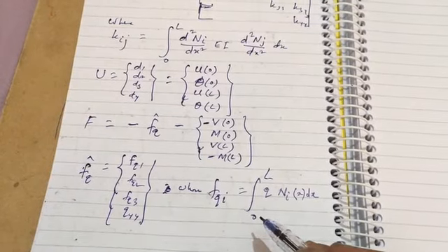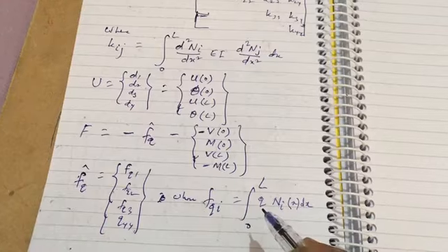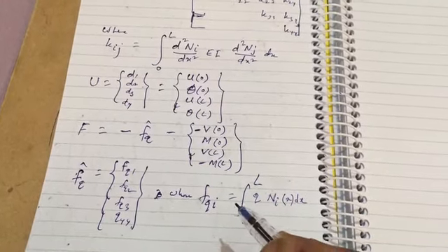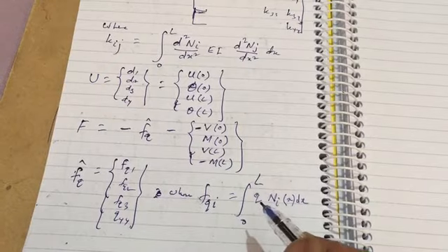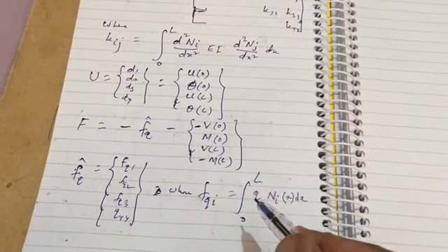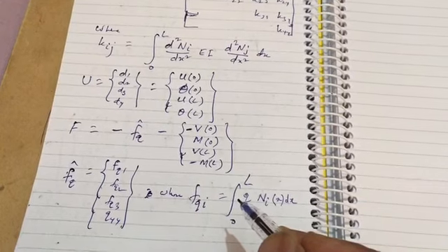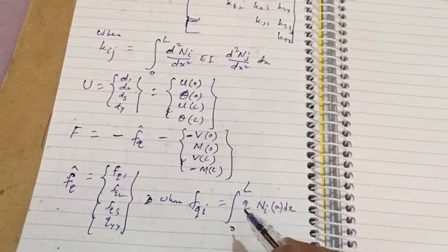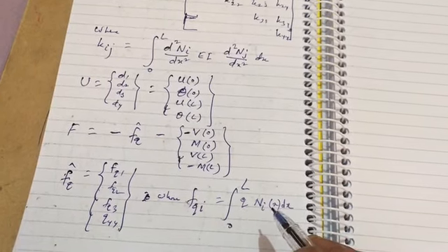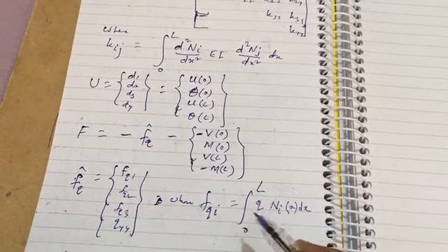This is similar to what we had in the truss element or the 1D bar element, where in order to find the force component we just had b, the body force, times Ni, where Ni is the shape function, of the same form.